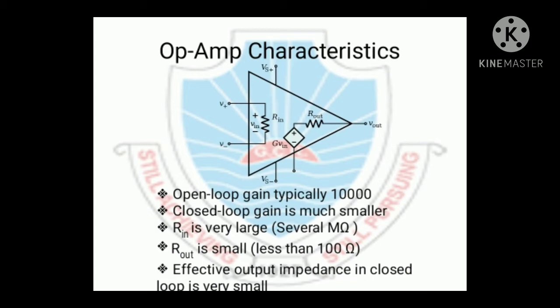As far as its input resistance is concerned, it is of the order of several mega ohms. So its input resistance is really high. It's not infinite, but it is very high. Also, its output resistance is very small, which is less than 100 ohm, or maybe you can say 50 ohm also.